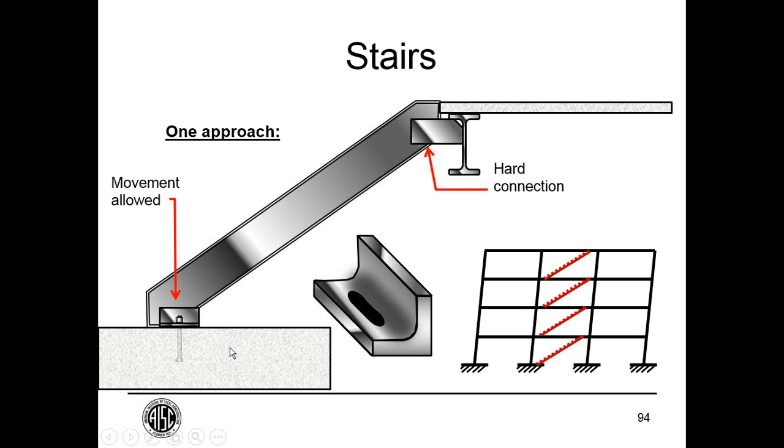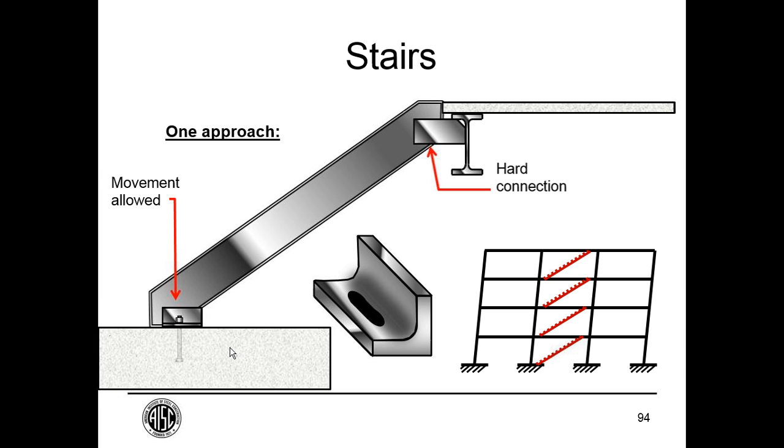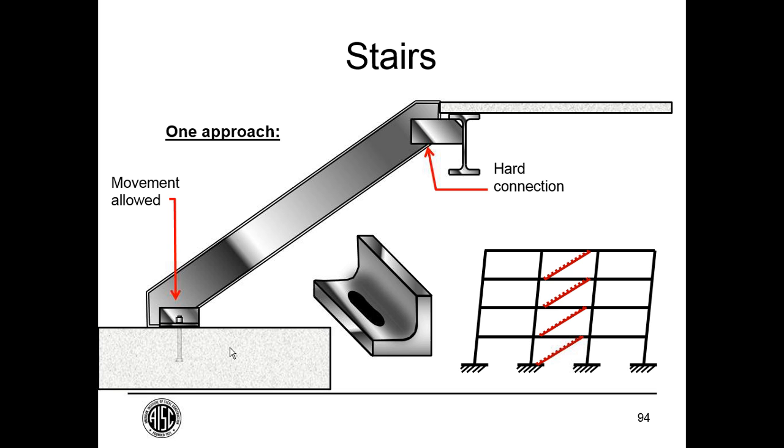Now there's also displacement in and out of the page, as we see here, and sometimes the stairs are flexible enough to handle that without any special detailing, but that's also something that should be considered by the designer. So as we get motion, and hopefully this isn't too jerky for anyone watching, you can see that the stair moves with the upper diaphragm and it's moving back and forth within that slot.